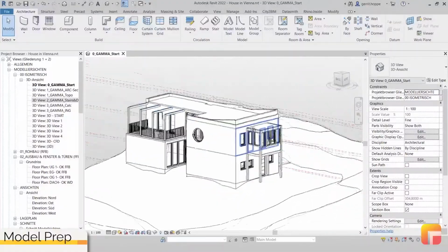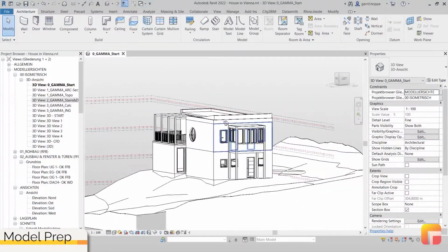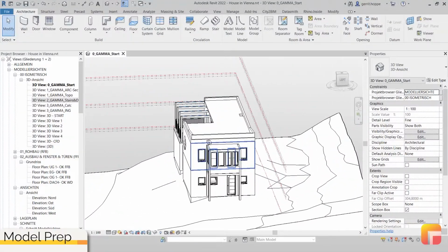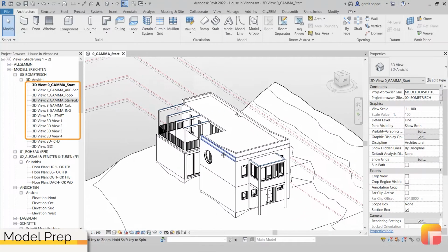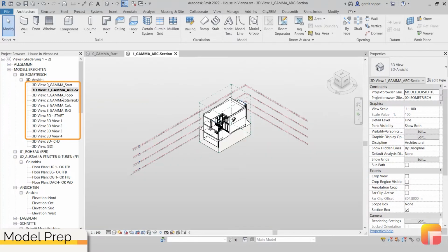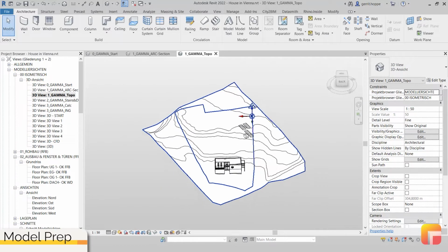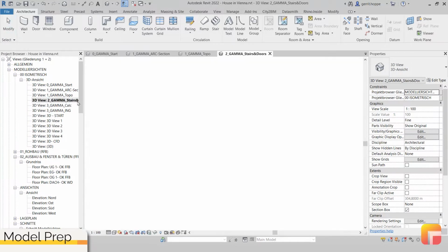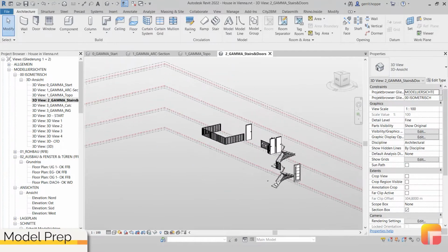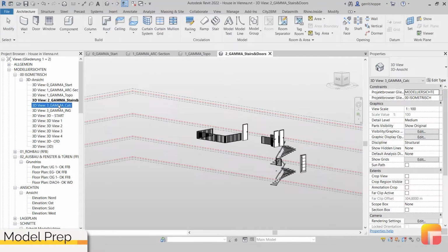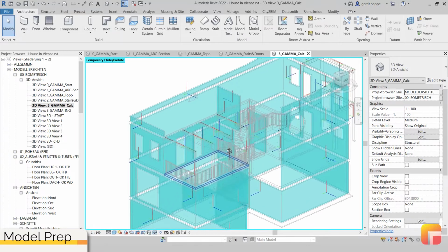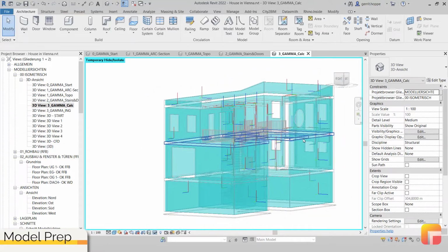Depending on your own workflow on site, you can prepare your model according to what suits your needs the best by creating custom views in Revit. Gamma AR is able not only to depict any 3D views easily, but also the planned phases as well. By exporting a prepared 3D view, you make certain that the app has 3D IFC rooms to work with. As 3D views can be completely custom tailored, we will walk you through some basic steps.